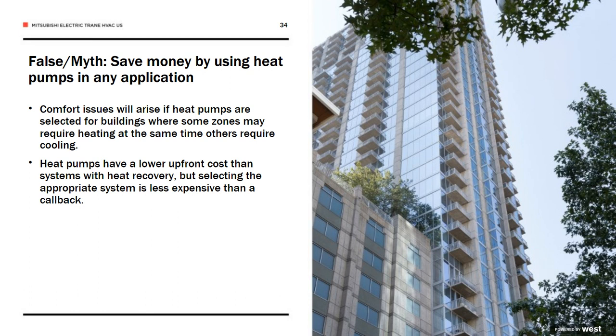All right. Another myth: you can save money using heat pumps in any application. That is actually false. If you have cases where you're going to need heating at the same time as cooling on a particular building, you really shouldn't use a heat pump system.